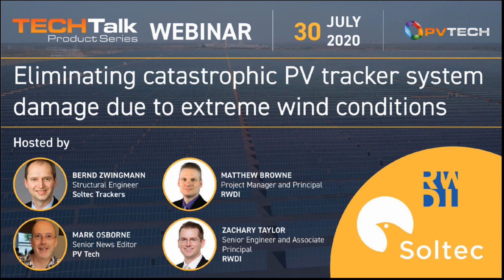So while module sizes are changing, while other factors are changing, there's a great amount of flexibility in the approach because of how well understood the aerodynamics are in terms of damping and stiffness, that we can provide some insight on different module sizes and different other factors that might go into the decision making. And then once we're converging on an answer, we go in and do a full aeroelastic study to confirm all that analytical work.